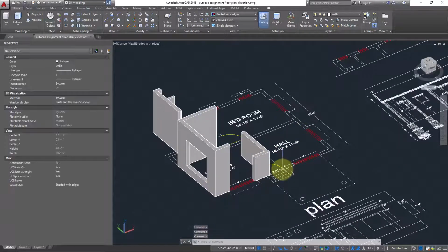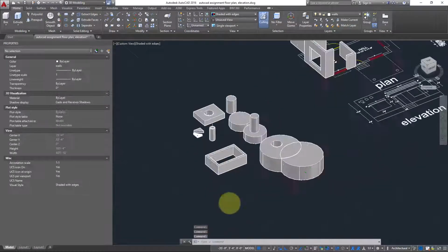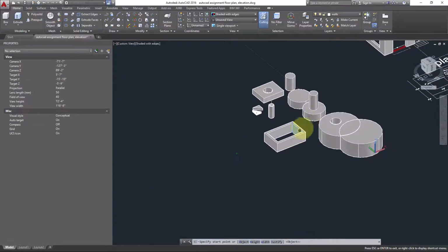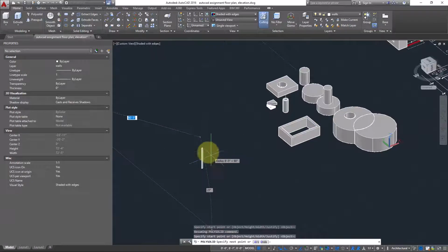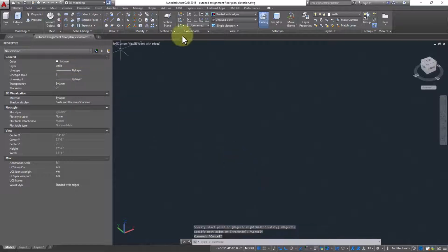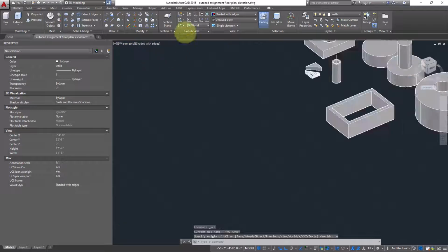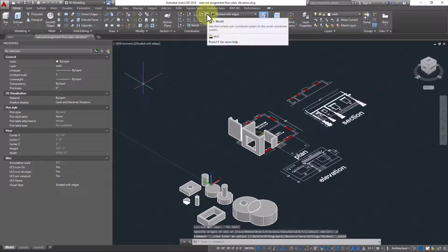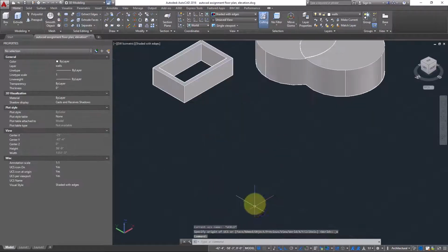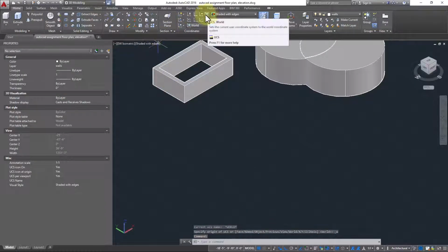Then we also have another amazing command, which is called Polysolid. The Polysolid command is used to create walls in your drawing. How? Just take this Polysolid command and click and drag, so it will create walls. Just click this side. So let me make a default plane. From here, SW, and you can also click from here in the coordinate UCS world coordinate system. If you made something wrong, just click on this option and Southwest.